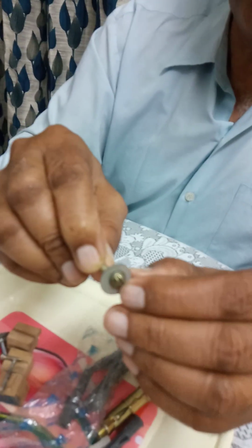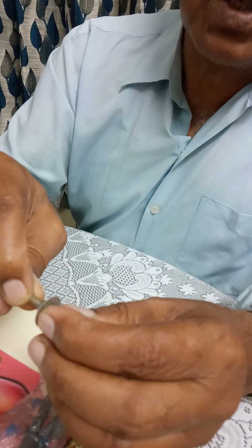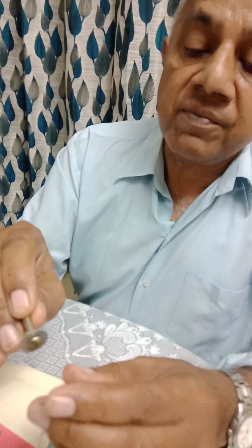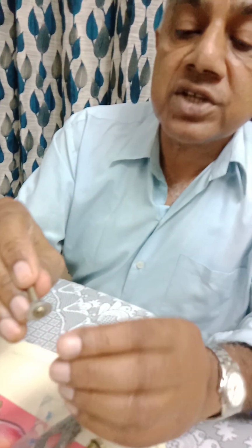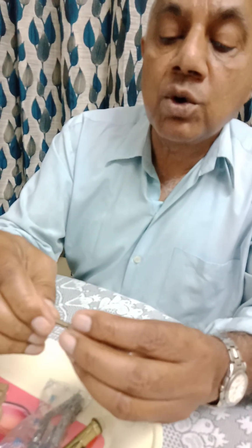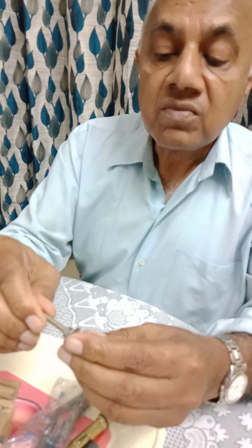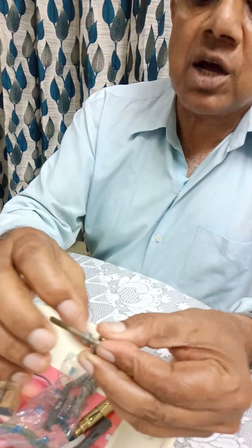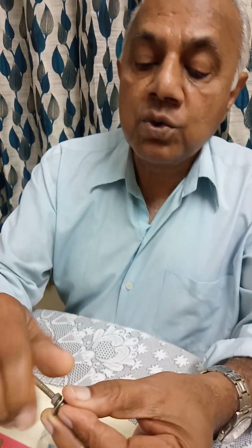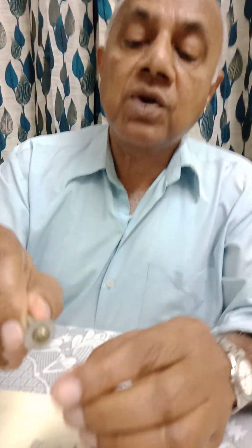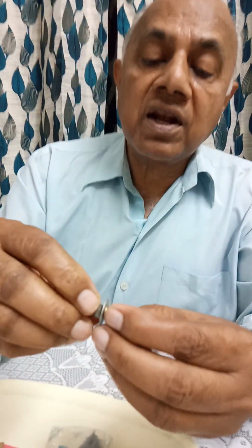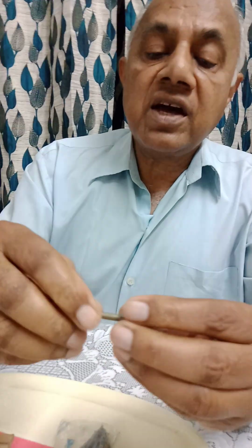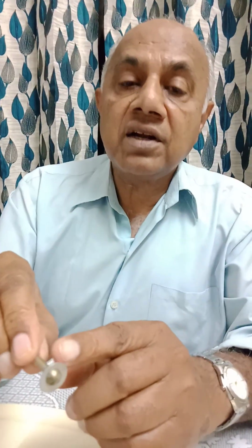So in order to prevent damage on this head, we use this kind of material. This is called a spring washer. And another role of the spring washer is that usually nuts and bolts are often used in different kinds of moving objects, and this nut starts getting loosened, starts coming out. But when we use this kind of typical spring washer, then this nut and bolt are held tightly and the nut does not get loosened.